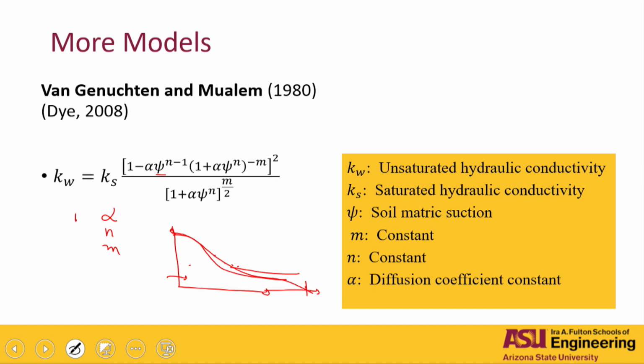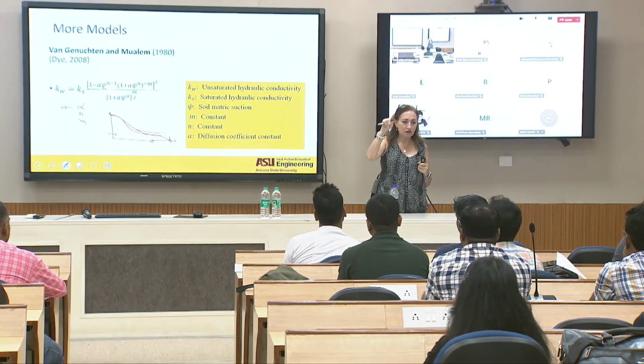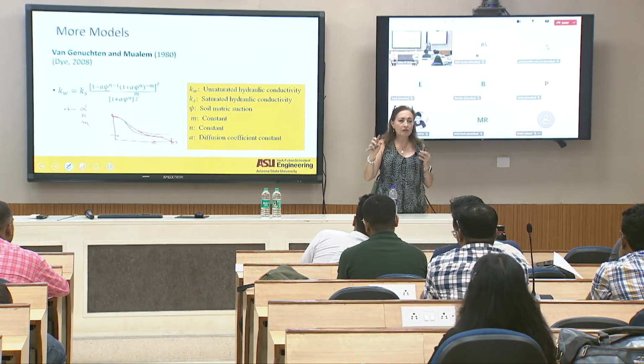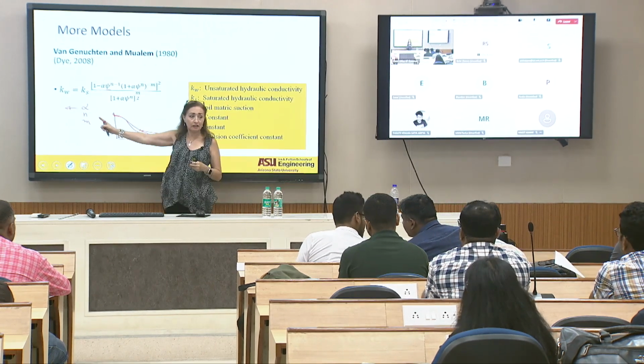Yes. Okay, and again, I'm a little bit critical about that, but yeah, it could be. It depends on whether you use the degree of saturation, volumetric water content, or gravimetric water content. For one of those functions, you can relate this one with the air entry value directly.